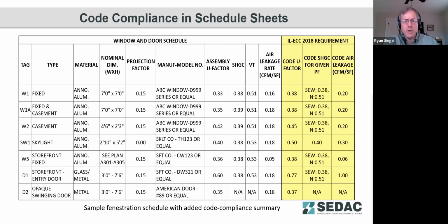And so you may select fenestration based on the direction, where you may want to take advantage of solar heat gain during certain times of year and during certain angles of the sun, and you may want to reject heat at other angles. So it's not uncommon to see windows facing different directions having different solar heat gains or U factors. So wanting to take advantage where we want it and not where we don't.